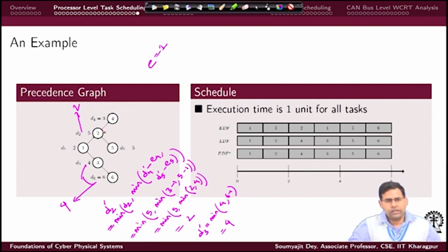One can even say that this example is kind of built to highlight this issue, because somehow we have kept this high and kept the deadline of the later nodes to be smaller, at least this one. The idea is we are trying to show how this guy is forcing the actual runtime deadline of these to change. Okay. So even in your precedence constraint graph, if some intermediate node has a higher deadline, it will automatically get pushed to the left by nodes later on if they have a smaller deadline. So that is kind of what we are trying to show here.